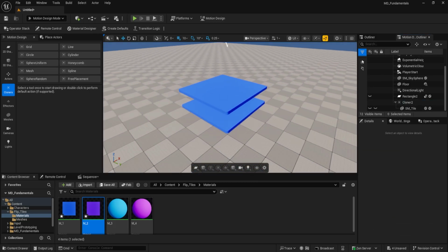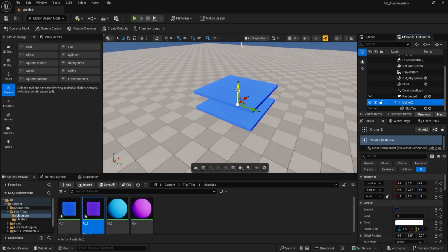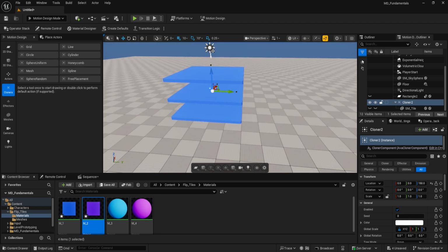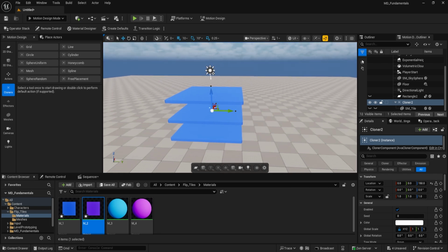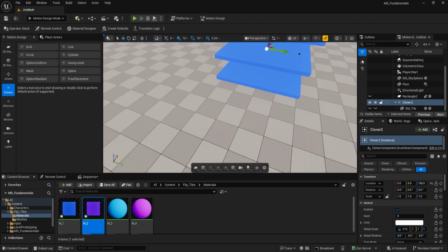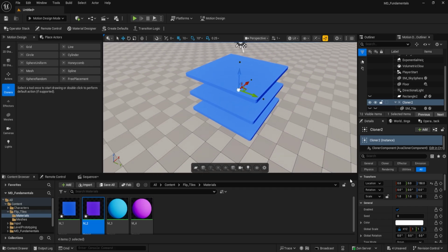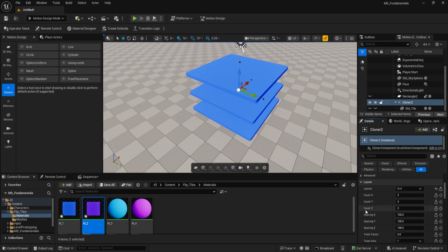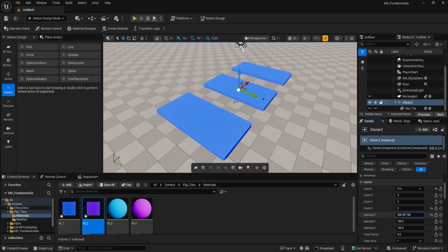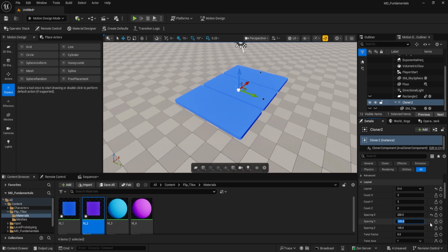And here you can see, if I put this cloner up, we can see 3 different tiles. It also contains the XY tiles, but those are merged together. So for this, make sure your cloner is selected and just go downward, change the Z count to 0, and if we increase the distance, we can see, so I think 200. Perfect, just 200.